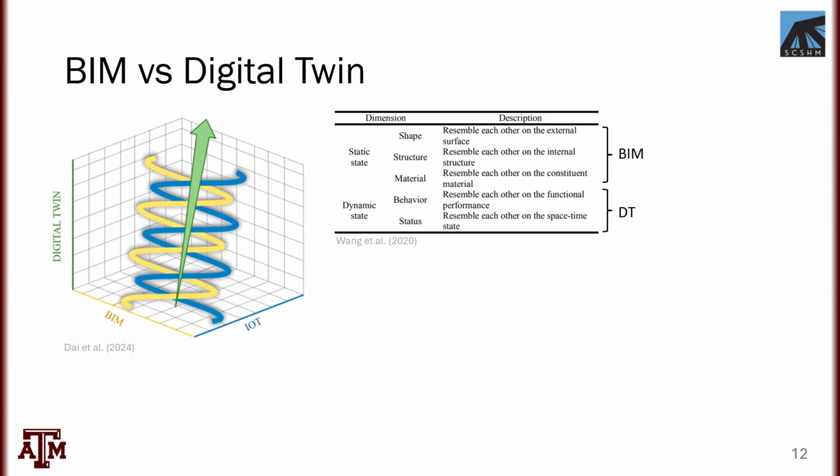But a digital twin, in contrast, will be a little bit different. It will extend these concepts by incorporating a variety of different data, often real-time data. It will enable behavioral, temporal tracking of the asset's behaviors. It will have predictive modeling capabilities. It will have some sort of a continuous feedback mechanism to help the actual physical twin asset. So that's really how I would describe it. BIM tends to be more static. Digital twin tends to be more dynamic.